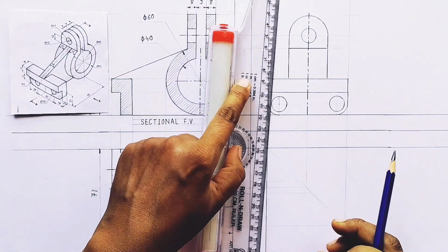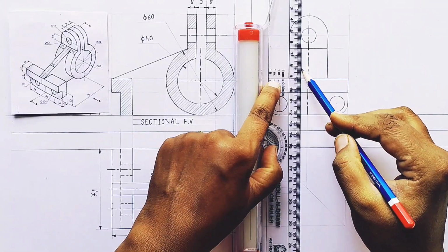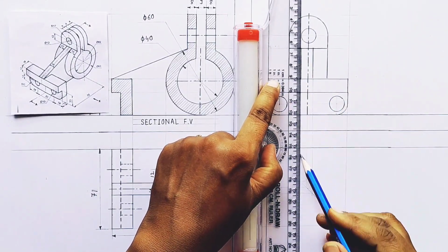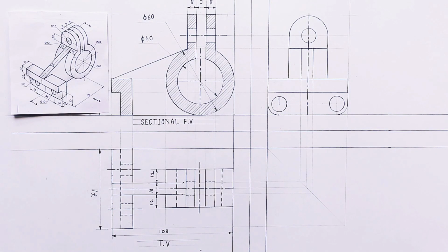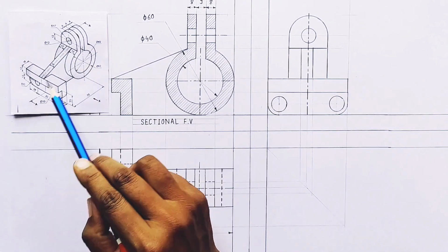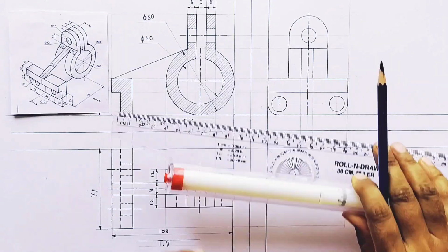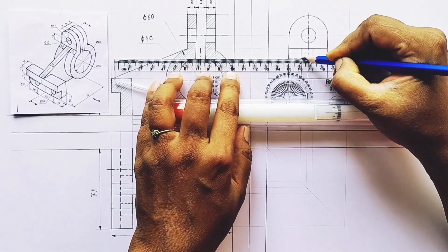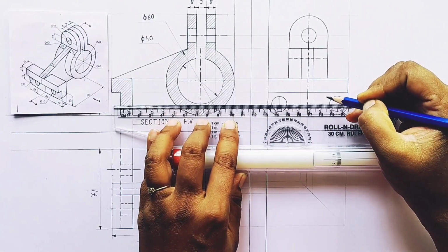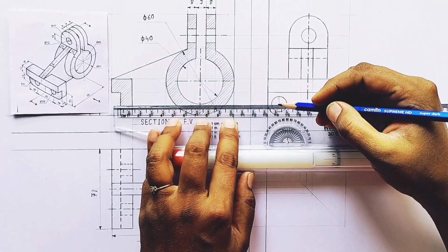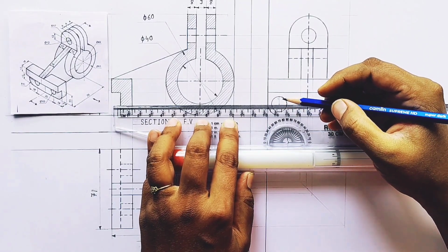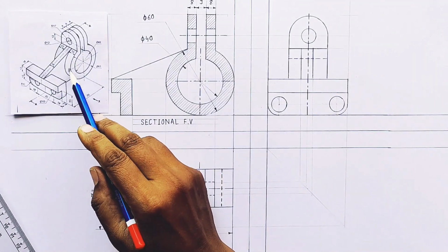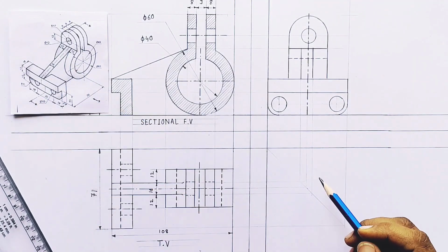Here the semicircular part of the side view is complete, and I am drawing the rib right now. So here see, my projections are always a little off, there is a difference of 1 mm or 2 mm. I take the projections of the rib and there is a difference. If you are good at projection lines, then take your projections from the top view, otherwise directly take dimensions. So here I draw a rib, then next